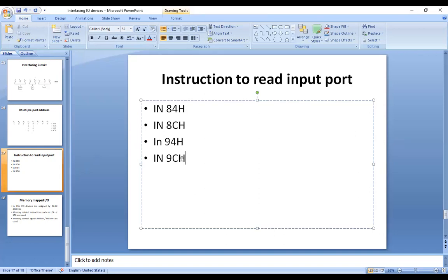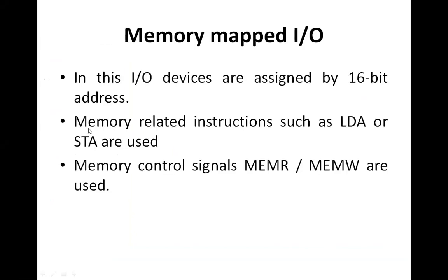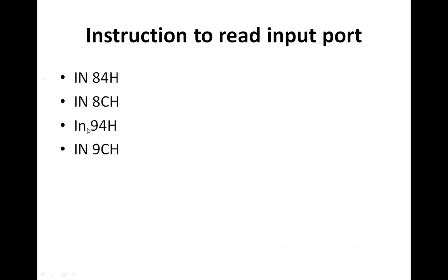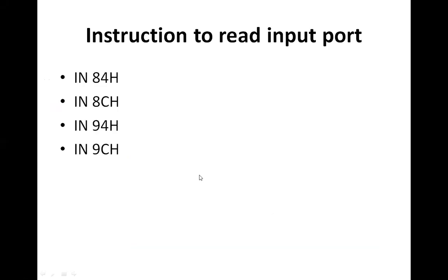Any address can be given, and if this address is being given, any one of these is going to read the same port. So to read the data from the input port, the IN instruction can be used, and when this instruction is going to be executed